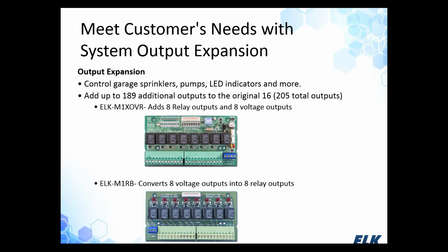I do like the relay board itself because it does give you that cool little LED turn on when that relay does click, in case you can't hear the relay click because your buddy or your coworker turned on the siren close to your head. Well, we've all kind of done that to each other growing up in the industry. But just to give you an example, it does have that. You can also use the M1RB on the main board itself and turn those flying voltage outputs, 9 through 16, into relay outputs using this particular board.